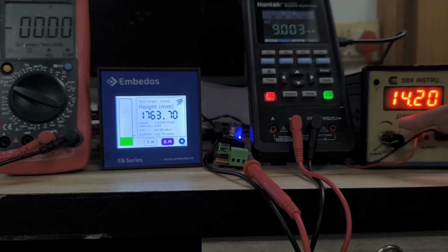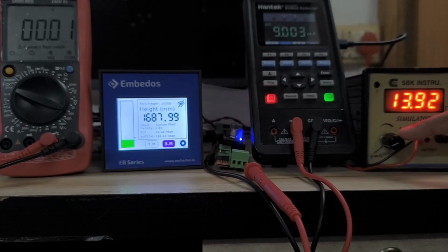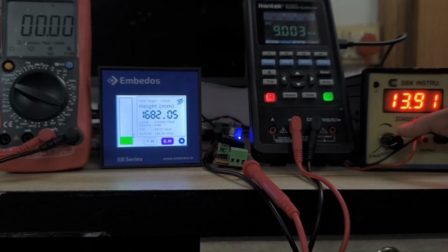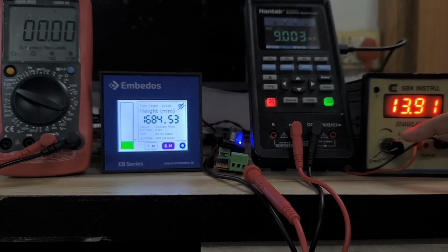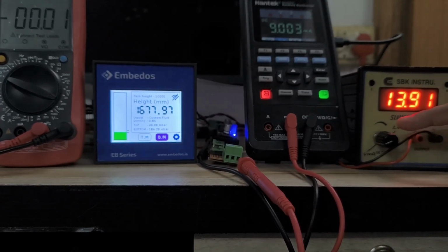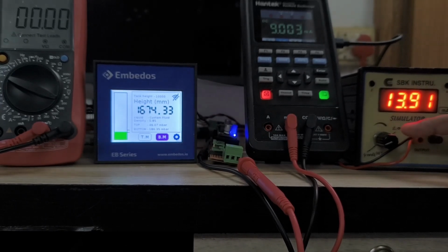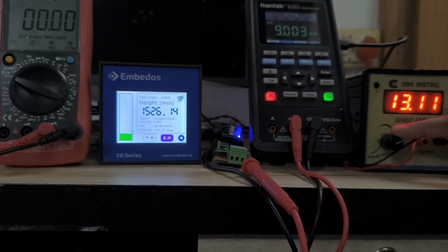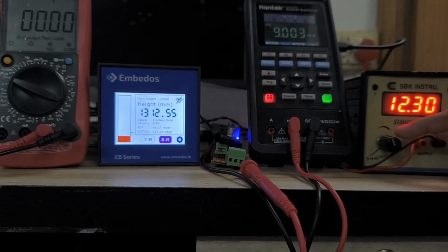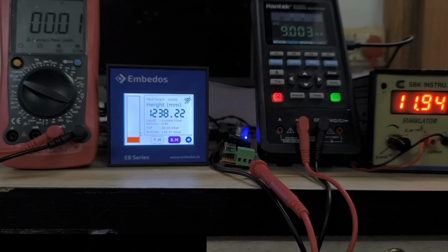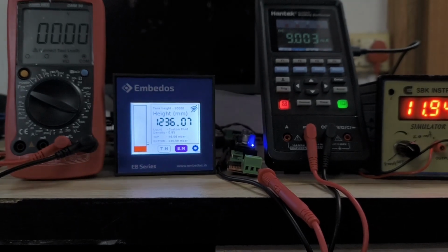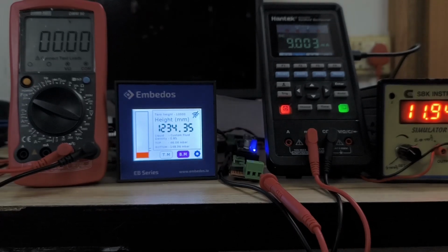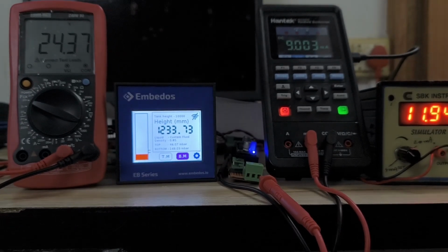The current configuration, the window function for the output is set to outside, and the set point is set at 1300, so when the value goes below 1300, the output relay is triggered. As the output delay duration is set to 10, the outputs will be triggered after 10 seconds and will stay high for 5 seconds.